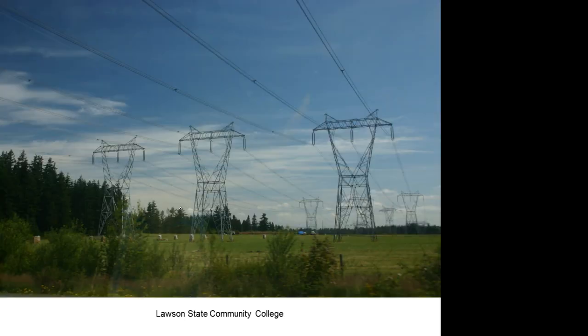And of course, I've seen these guys all over the place. 3 nice big wires. They usually run them in groups of 3s. What that does is it allows 1 wire to break and there's still power, and it also reduces the gauge of the wire. If you hook 3 wires in parallel, the current would split up between the 3, and each conductor itself would only be carrying 1/3 of the current. I've never seen them run more groups. So it allows them to use a smaller gauge wire, so now they can put it on a spool and unspool it. And also it's aluminum too.